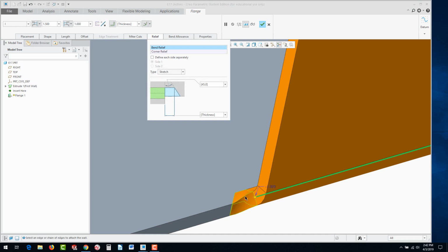And you can see there, as if there was no relief cut put in whatsoever, it actually bends the sheet metal, gives you that little ripple effect. So you have the ability to change that. Or you could go to rectangular. Rectangular is typically used if you laser or water jet or plasma cut something, it's easy to make that. But if you're die pressing something, obround is the more likely one that you would choose, simply because the wear on the die would be reduced due to the radius. And that could vary depending upon, again, your application.